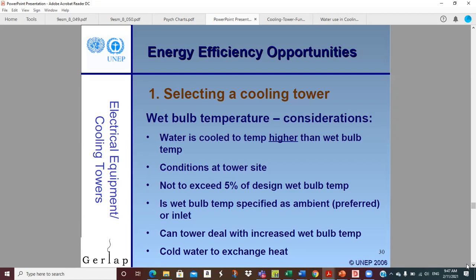Or you may have a whole line of cooling towers where the moisture put up by some of these other cooling towers, by recirculation, is going to get pulled back in to yours. And so just using the ambient weather data can be a dangerous thing. So you have to really consider the actual location where this thing is going to sit, and then look around and see if there are any moisture sources close to it that would affect your sizing.